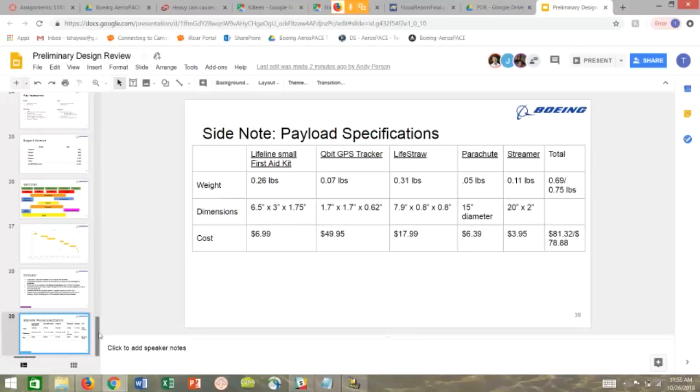And that would drive the propulsion unit to the back of the fuselage, and because you are releasing the payload, again, the payload should be centrally located around CG in order not to affect your balance during the flight. So I really like your concept of a very simple latch payload release.